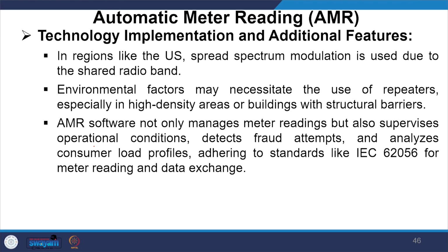In regions like the US, spread spectrum modulation is used due to the shared radio band. Environmental factors may necessitate the use of repeaters, especially in high density areas or buildings with structural barriers. AMR software not only manages meter readings but also supervises operational conditions, detects fraud attempts, and analyzes consumer load profiles, adhering to standards like IEC 62056 for meter reading and data exchange.